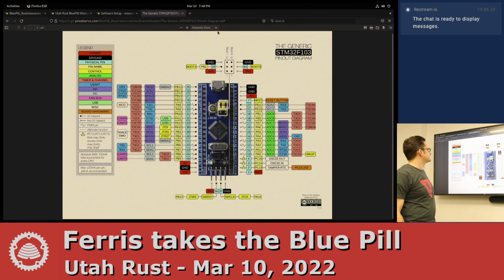This is the main external system clock. This below it is actually another clock. It's a 32K clock versus 8 megahertz. Typically you have a 32K clock hooked up to the real-time clock inside the system. We've got a reset button, which is always handy.